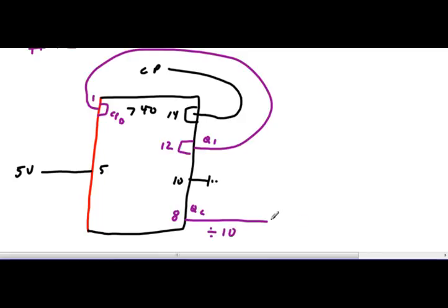Alright, now the issue is, what do I do with R01, R02, R91, and R92, which are control circuits to the decade counter? So now I'm going to look in the front of my book and see if it sheds any light on that issue before I punt. Alright, so 4592, and it says that that's master reset 1, master reset 2, and that pins 2 and 3 are not connected. Oh, wrong guy.